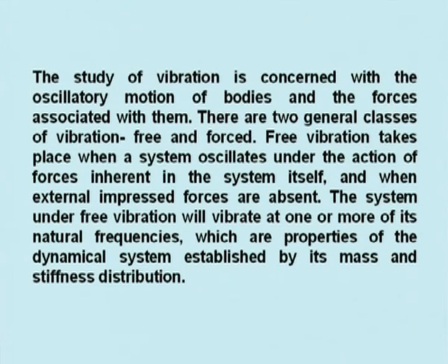Now, if we take a spring mass system and disturb it for some distance, that means we displace the mass by some amount, then in that case this motion of the mass starts, and this is called free vibration. The spring force is always present, and at the same time you have inertia force. The body is under equilibrium under the spring force and inertia force.